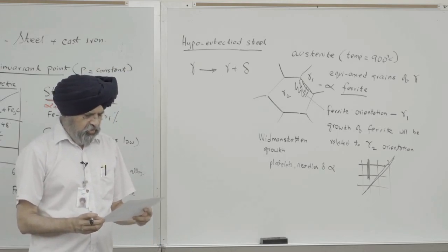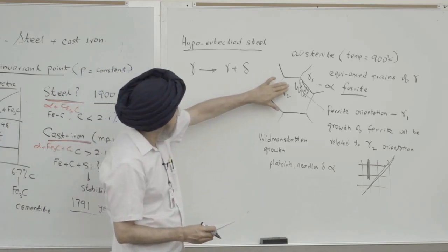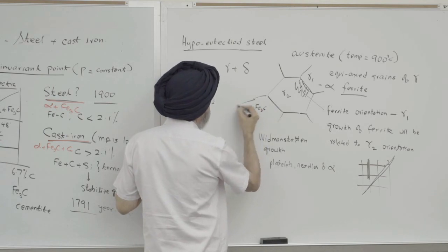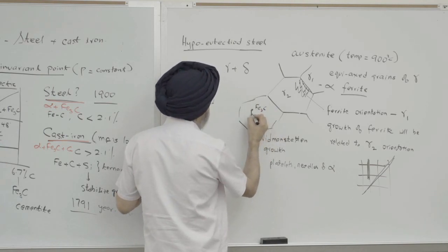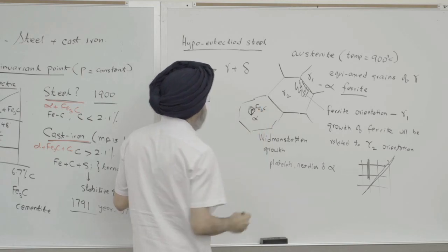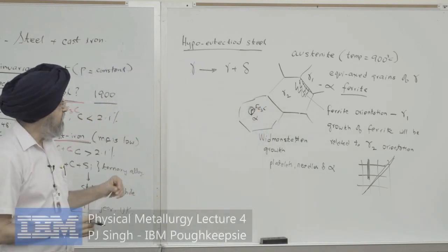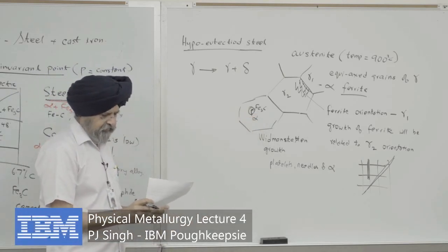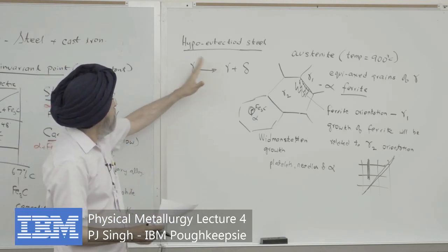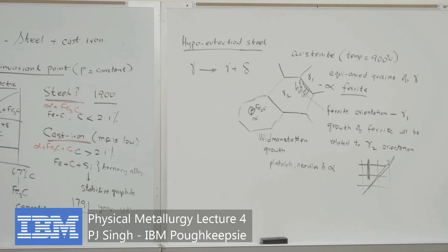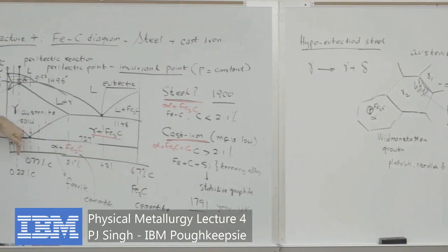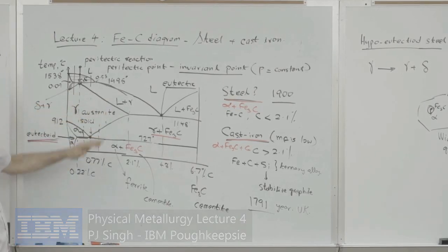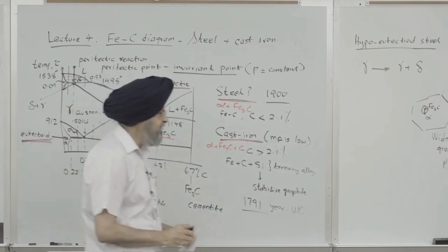Okay, so as I mentioned earlier, if you have any Fe3C within the grains, the alpha can also precipitate on the Fe3C. And if it does that, it'll have a relationship with Fe3C in terms of orientation. So that's the hypoeutectoid steel. Hypo means below the eutectoid in terms of composition, and proeutectoid means above the eutectoid temperature. So these are terms which can be a little misleading.